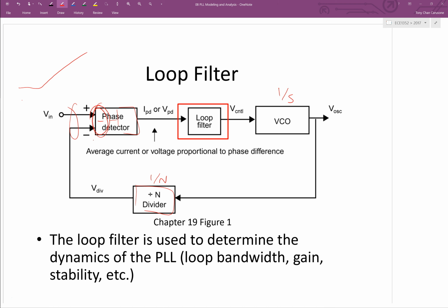It would try really hard to track this frequency difference. But what you would see in the fed-back divided down clock is it would lag behind it, right? So maybe I can see people like gears churning, sparks flying from like undergrad, but that's what you get with a type 1 loop and a ramp input. It follows it, but there's a lag there. So what does that mean?